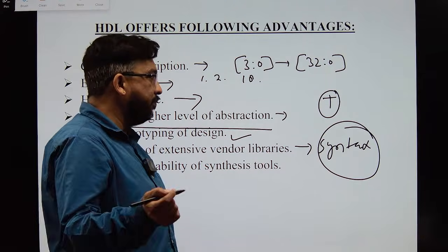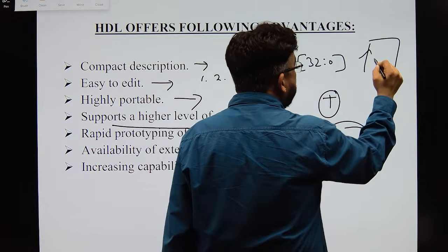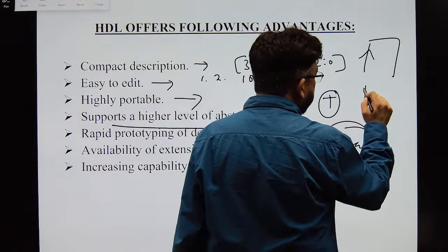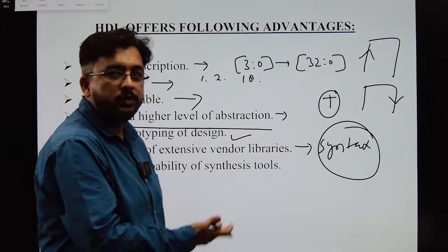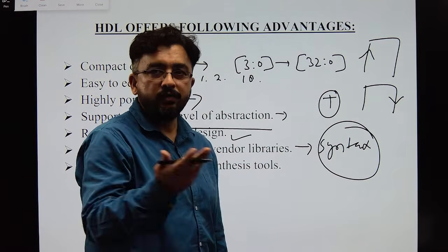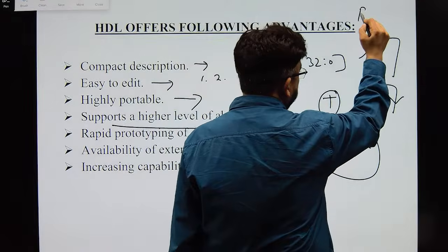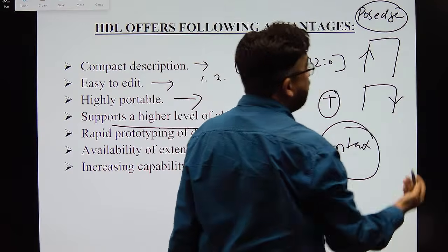For example, I want my output to be transferred on the positive edge, or I want my output to be transferred on the negative edge. In Verilog, you will use posedge. In VHDL, you will use the same thing. So posedge is one of the library constructs or syntax.